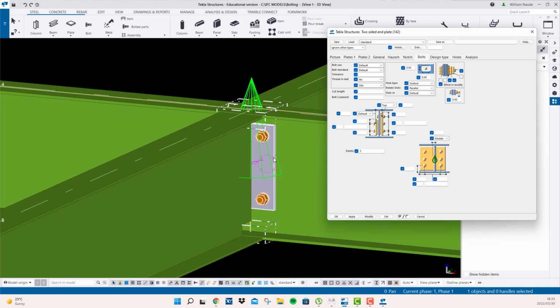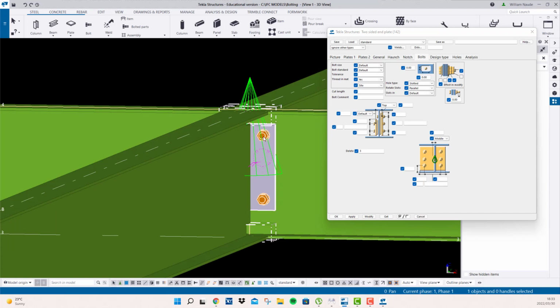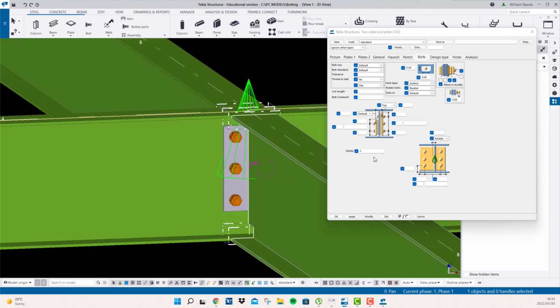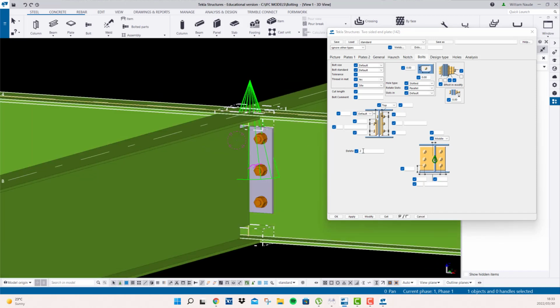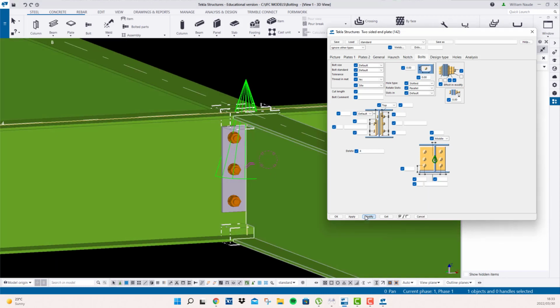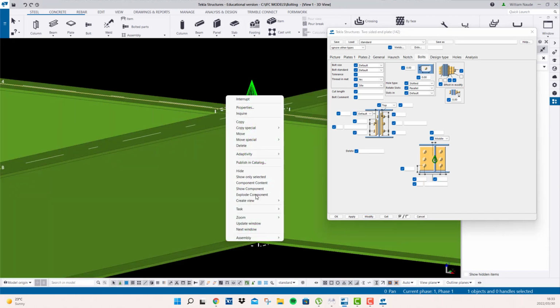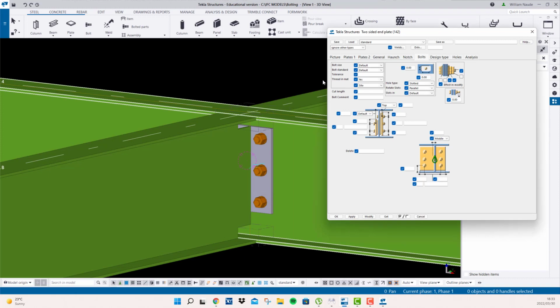As soon as I say modify, it removes that bolt, as you can see, because it will count probably 1, 2, 3. So if I choose rather 2, it should be this bolt right here. 1 is on this side right here. So 4 would mean it will delete this item right here. So you can either do it on your component itself, or another method of doing this would be to explode your item doing the following.